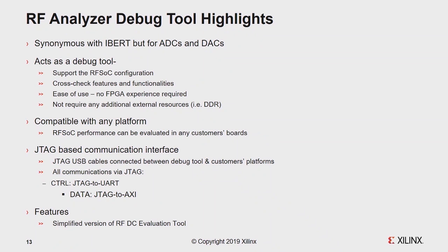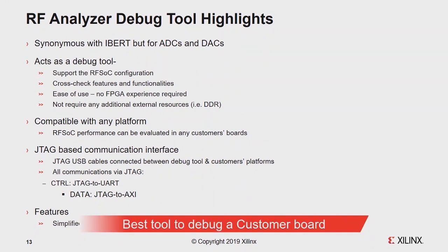It uses all the resources of the FPGA. You can now, still kind of based on GUI, bring up the DAC and the ADC and see if the customer board's working and debug the analog stuff without having any other tool involved. So it's a great tool for that, and consequently, I'm going to say it's the best tool to debug a customer board. You can do other things with it, but that's ideally what it's there for. And again, that can be downloaded from Xilinx.com. Okay.